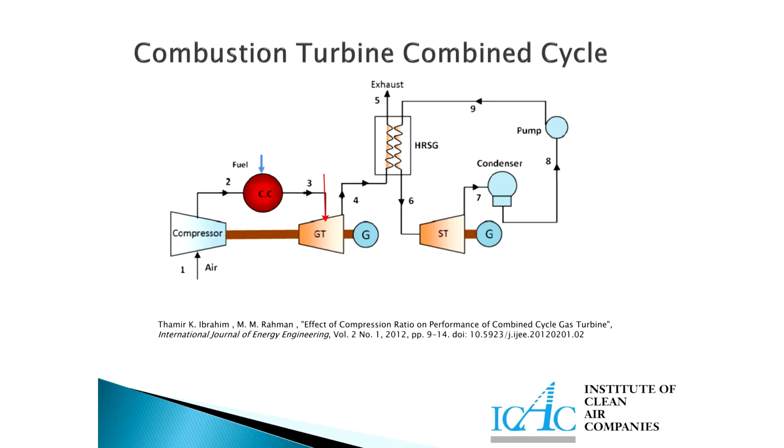You take the exhaust gas from the combustion turbine and you run it through a heat recovery steam generator, which is nothing more than the boiler that I described to you earlier, except that it doesn't have a flame in it. All it has is a hot gas. Then obviously the exhaust you send out the stack, but the heat recovery steam generator makes steam, which goes into a steam turbine and a generator, just like the coal unit has, and then it goes to a condenser, and back up again, gets recycled, and the cycle starts all over again.